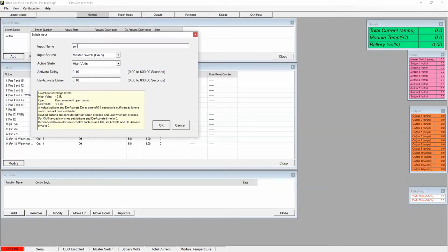Switch. Let's do this one, switch 2. So let me just find that on the pinout. Switch 2, I remember what it is, but I want to find it and double check. I think it was starter. Okay, input. Switch input to starter. Okay, it's pin 32.